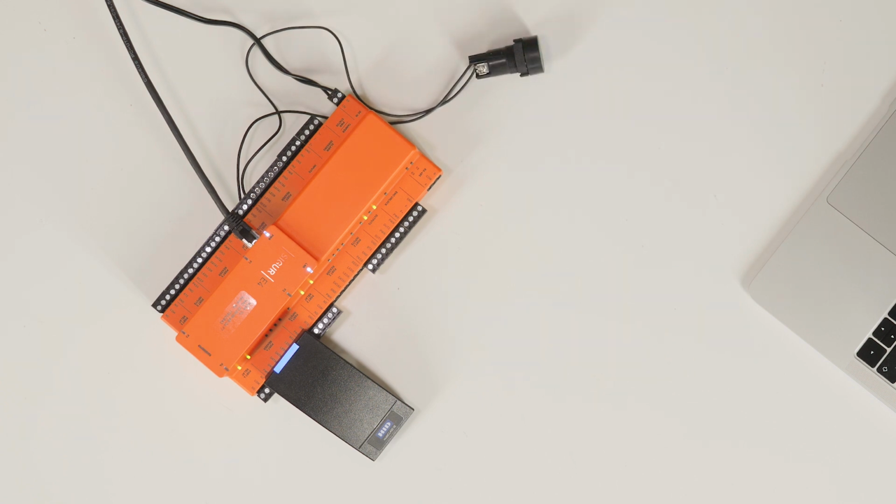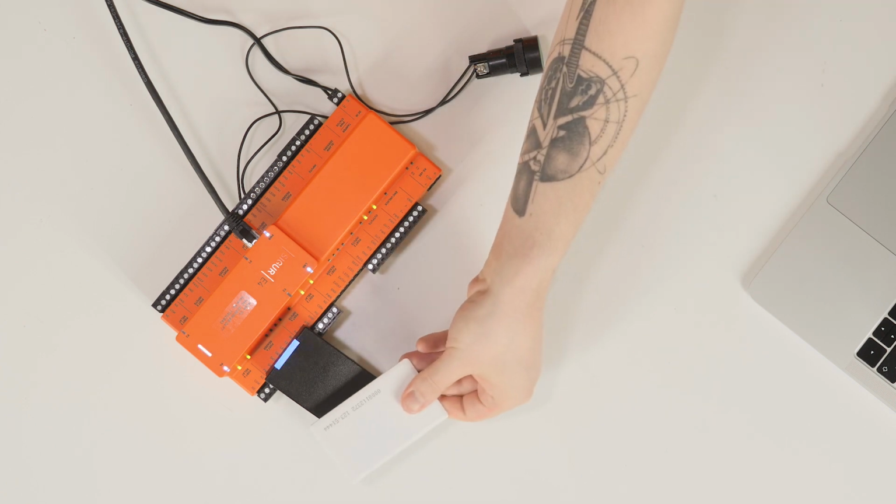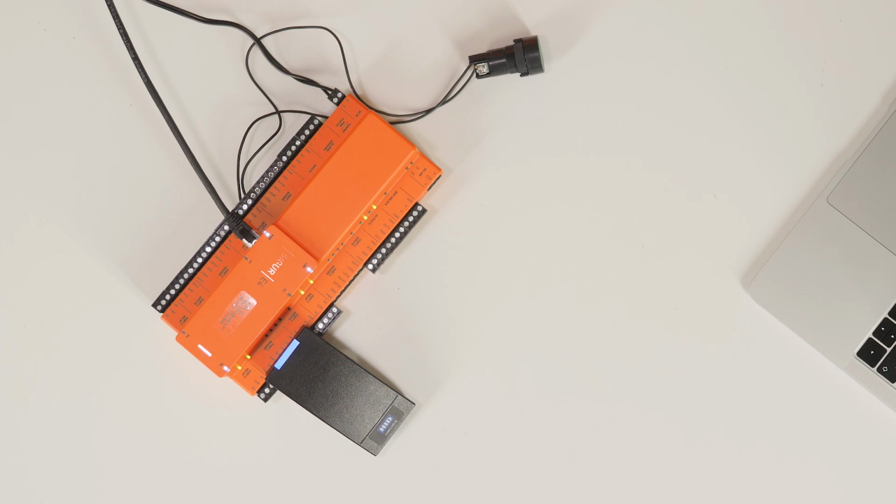Now let's change the access point to an unlocked state and then to a locked mode. We observe the corresponding signal from the reader regarding the status of the access point. And finally, let's consider the indication in case of an unusual event of waiting for the accompanying person. Let's present the employee's card. We observe the indication of waiting for the accompanying card. We apply the administrator's card. The reader reproduces access permission indication. With this, the reader configuration with separate lines for controlling the indication is completed.